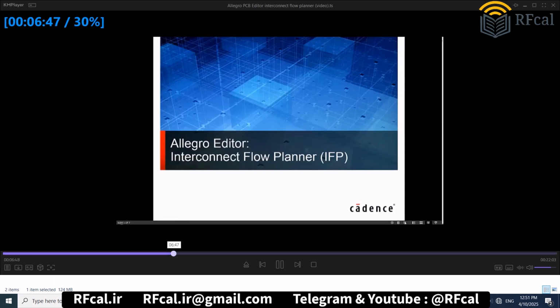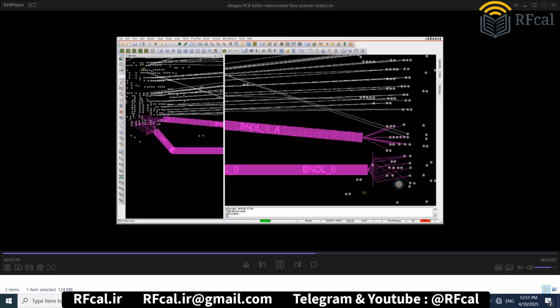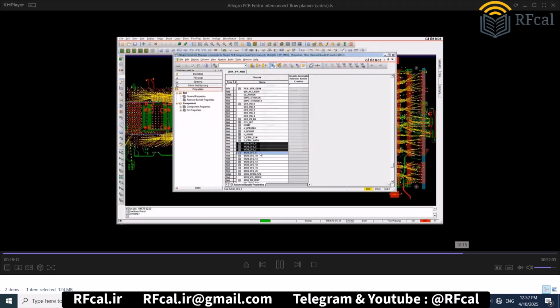Hello, this is Mark. Pin proximity and connections and connectivity for bundle generation. As I grab that endpoint, you'll notice that the rake converts itself into what is called the extended routed bundle, and we've provided a specific direction that we want this particular bundle to be routed in, and we can say that we want specific nets to create a bundle, or if we wanted to add these to, again, a different